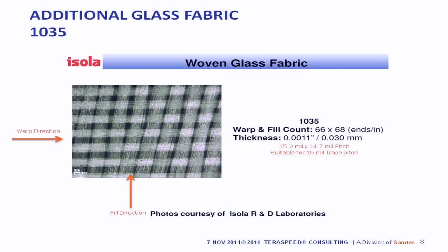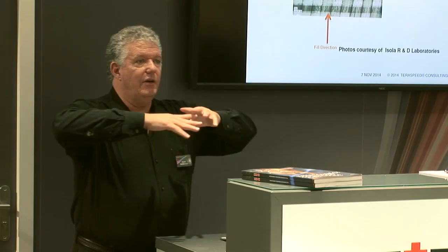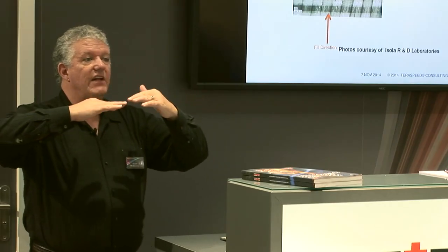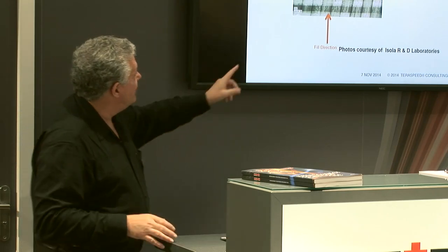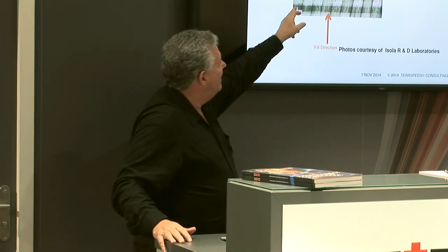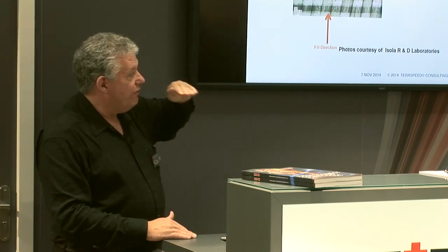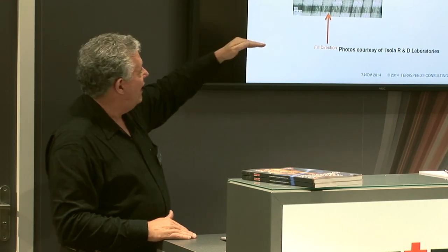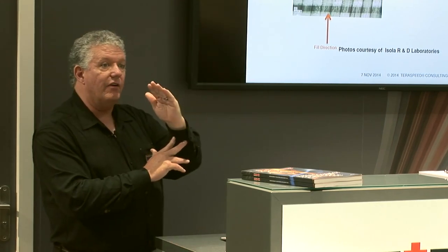And this is one of the interesting things about fiberglass. Just like any fabric, if you were to take fabric and roll it out on a roll and try to pour a liquid epoxy over it, it would move. And that's known as weave wander. And you can see that in one direction, the fibers are completely parallel, yet in the other they're diagonal.